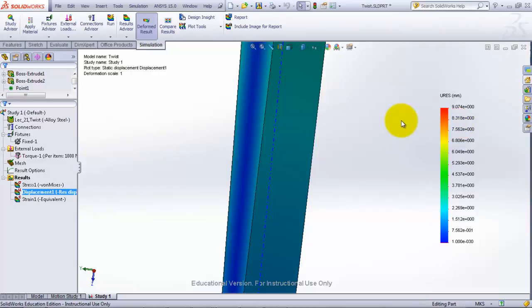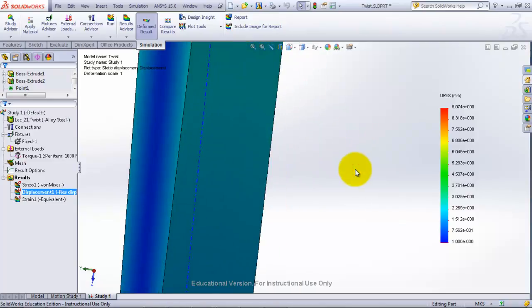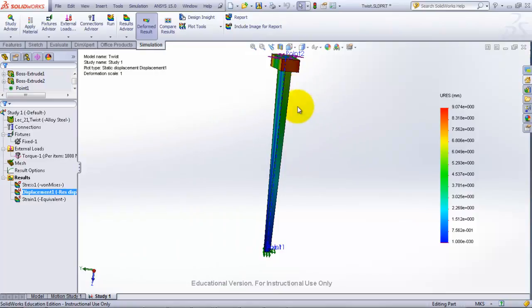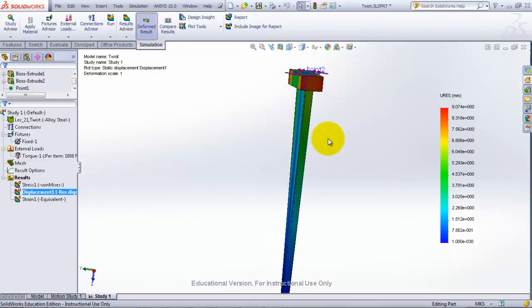Again, depending on what kind of accuracy you're looking for, you could go with the previous one. But ultimately, you want to keep reducing from 0.01 to 0.005, 0.003, 0.0025. You keep reducing until when you reduce it one more time, it doesn't change much. Then you can go back to the coarser mesh between those two, and that's the one you can use going forward, knowing that it doesn't change much if you make the grid any finer. So that's a great way to verify your mesh, confirming that the elements are sufficient to demonstrate you're capturing all that's happening in the case.